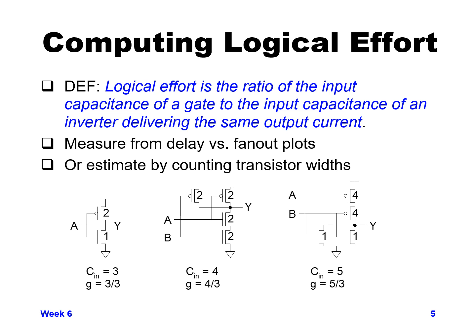We take the Cin for either input, which is going to a PMOS of size 4 and an NMOS of size 1. Add the 4 and 1 together, we get a Cin of 5. Normalize that by dividing by the size 3 inverter normalization, and our logical effort for a 2-input NOR gate is 5/3.